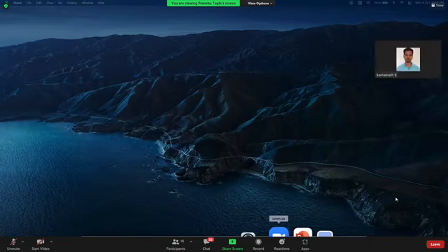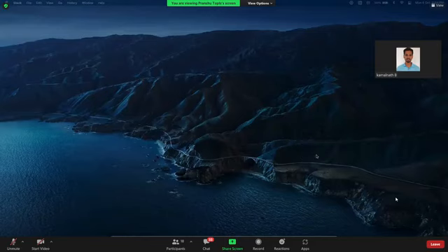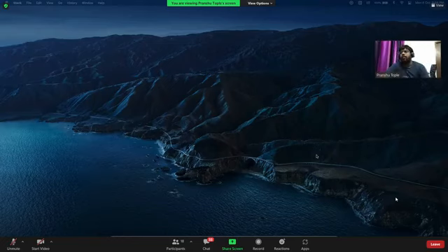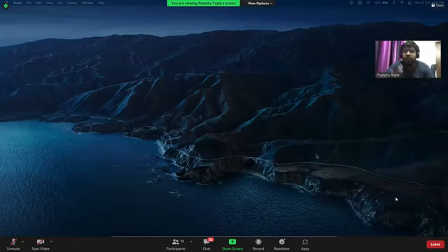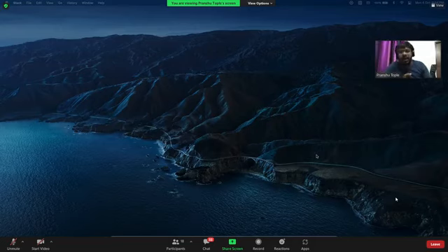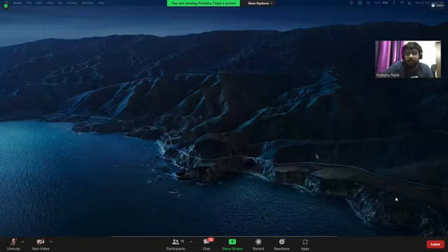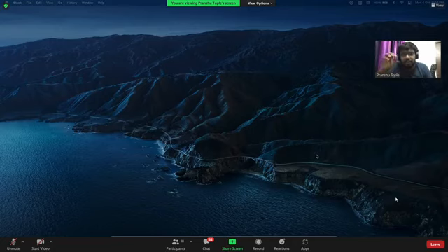Like in the case if the power gets cut down, for that case you need to implement your SLAM technique. Whatever you are doing for SLAM, in each house, once you have created the map of the house, then your AMCL should be powerful enough so that your robot localizes itself and knows where it is. If you search for auto AMCL, auto localization, you will get a lot of packages in which the robot checks its position at different places and automatically localizes itself. It knows at what position it is, and once it knows that, it can resume its work.